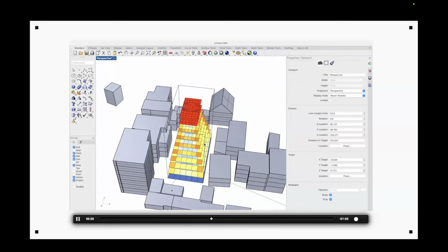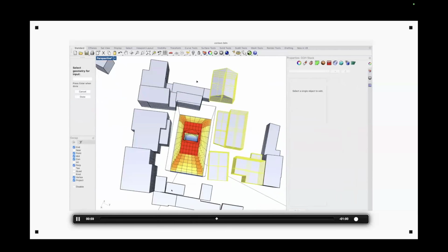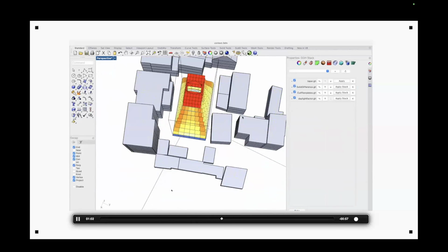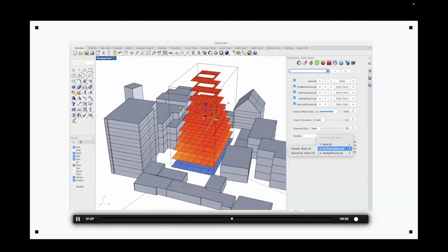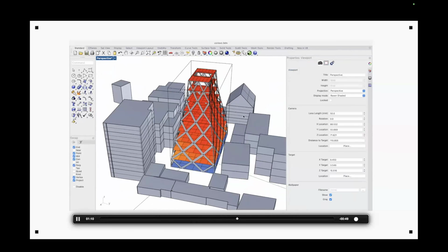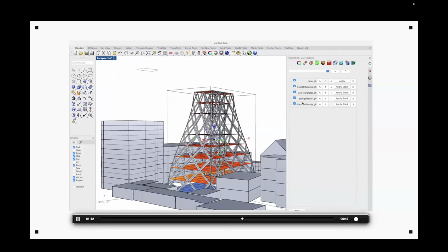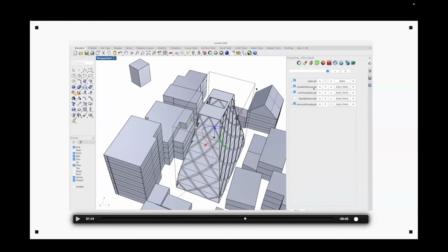So it's like referencing a box in Grasshopper. And you could have made one Grasshopper script that does all of this. But this way, it's much more maintainable, because I just know, oh, I'm going to be tapering things every now and then. So I just save one small Grasshopper script that tapers objects, and then one small Grasshopper script that cuts them into floor plates. And here you see this entire building is now just basically a cascade of Grasshopper scripts. So first this, then that, then that, then that. All of these get executed. One of them is even a Ladybug script that calculates a daylight factor on the floor plates. And they're executed sequentially, and they all have a little UI, so you can change how big the diamonds of the facade are and all of these little things.